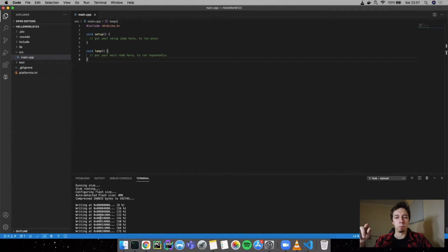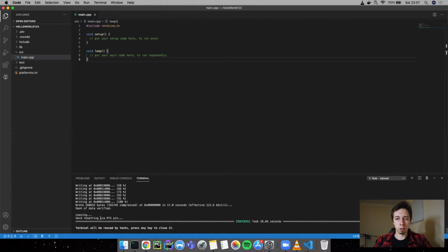One thing that I need to mention, and this is very important: you may get a connection error. The main reason usually is the cable, because some of the cables just don't work with ESP8266. You're still using the standard USB to micro USB cable, but some of those cables don't work with this device and some do. I had to test like 4 different cables, and only one of all of those worked for me.